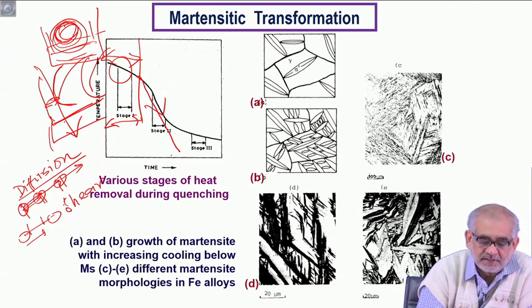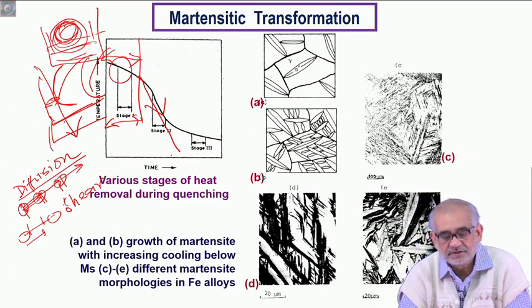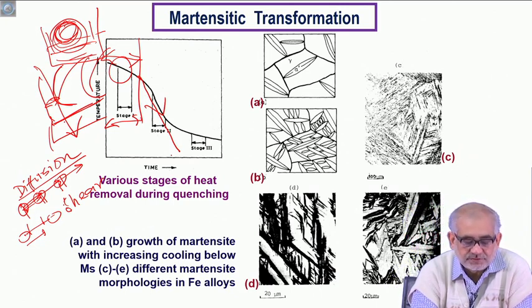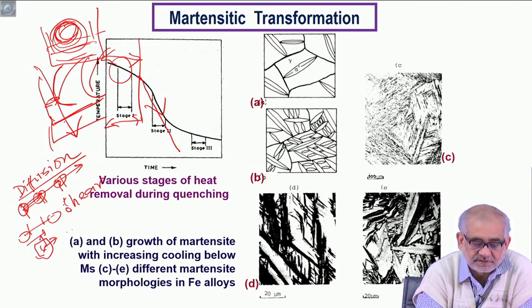Now, when we talk of Martensite, we need to understand that here the product is not going to form in an equiaxed shape, like growth in all directions to the same extent. This will not happen in case of Martensite, since it is a process dictated by shear, and shear of a set of atoms in a given direction only by a fraction of interatomic distances.